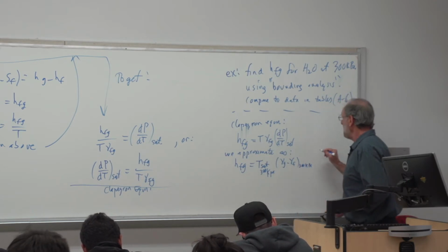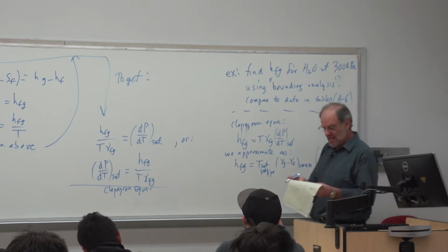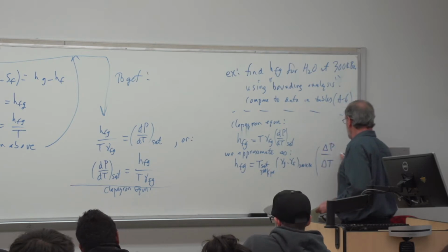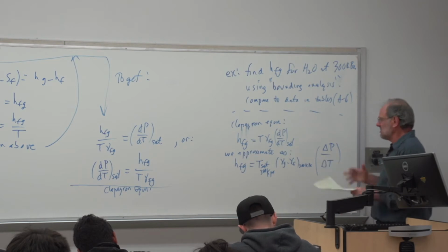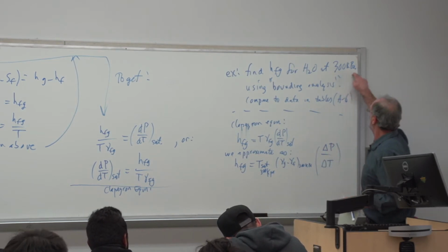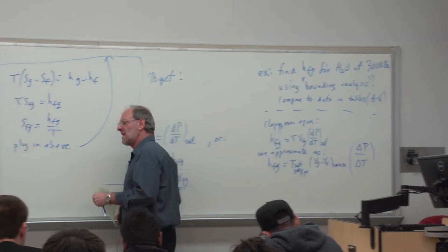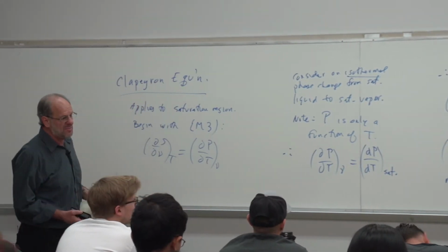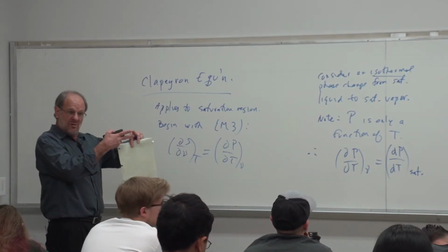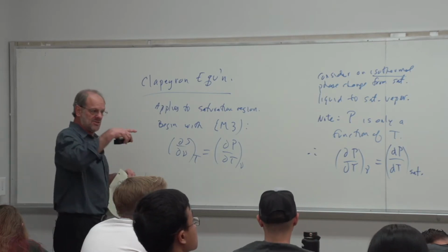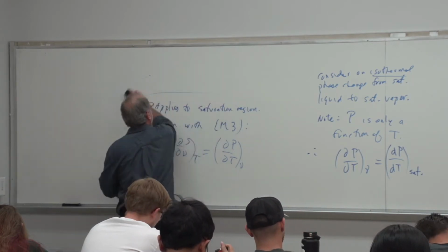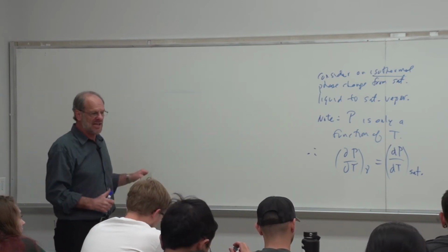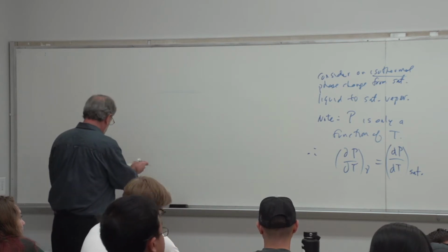Okay. And then dP dT, well, here's where we're going to have to actually do our bound. Here we could just write this as delta P over delta T, and then go into our tables and just look at the data and see what data bounds this pressure of 300 kilopascals. In fact, what you'll find is that in these tables, there's going to be another table at 275 kilopascals. That'll be one subtable over, if you will, from 300. And then there's another subtable to the right, which is at 325 kilopascals. So that's where we're going to take our bounding data. Again, it's as if we were in the lab recording all this data ourselves.